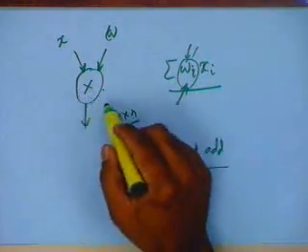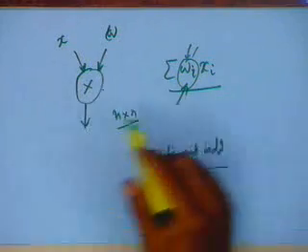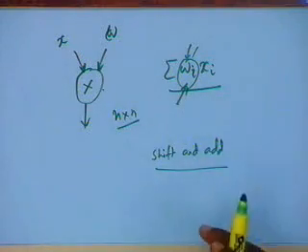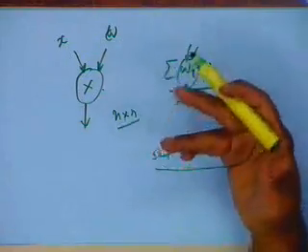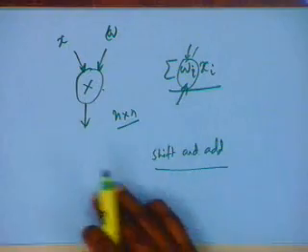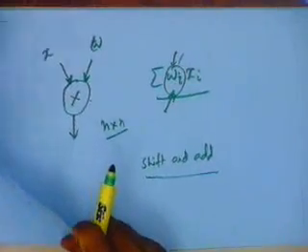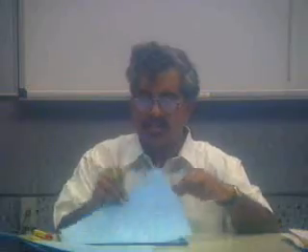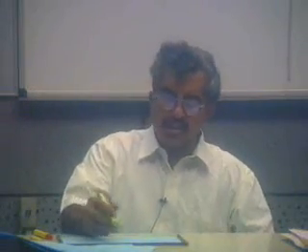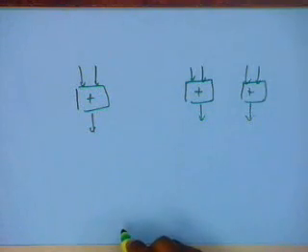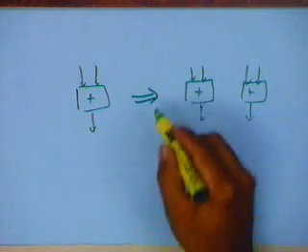So there are a number of trade-offs that can be made, finally deciding to replace an operation like multiply by shift and add, where you are doing only a few additions and not all the additions which a general multiplier would require. So these are some of the types of changes. For example, even architecturally, because we can change the frequency, let us say in a situation you just need to compare performing one addition, I can actually use two adders. I want to replace this by this.